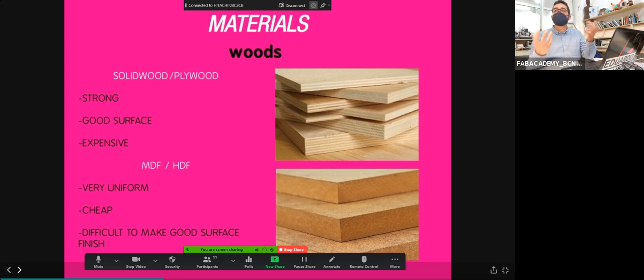The problem with compression cutters is they are quite more technical because as you're cutting up and down at the same time, you need to cut your board at once. And that means your chip loads are completely different. The chip load equation only works when you cut half of the end mill diameter. If you cut your material at once, the speeds and feeds are completely different. And you need to know how to estimate.